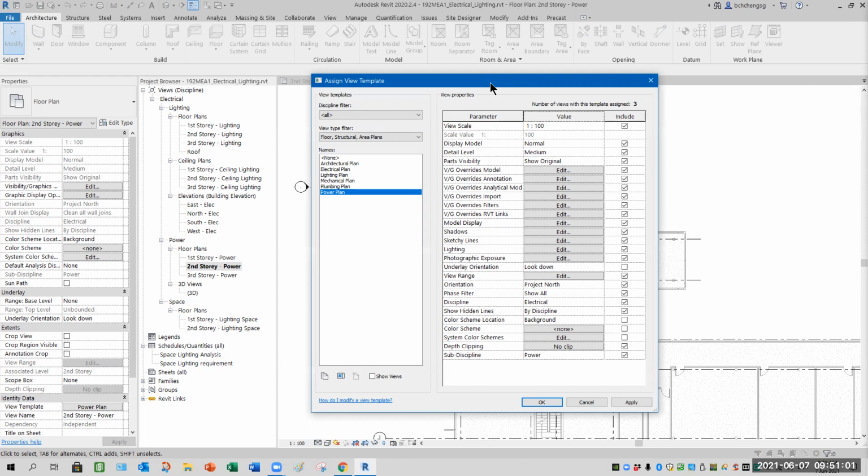For those who have not adjusted, please do so. Only the one that is Revit link, RVT link, is checked, right? The rest I want to uncheck so that we can manage that separately. Okay, yeah.